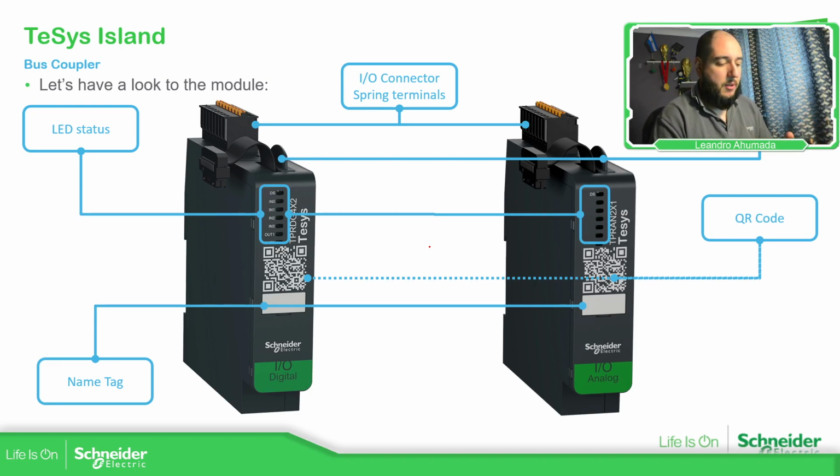Then we have in the back part the possibility to connect with the rail DIN. Over there, you have all the characteristics of the digital inputs and outputs. So, for example, for the analog inputs, you have voltage, current, you have, I just read it in front here, PT100, PT1000, thermocouples, and then for the outputs, voltage and current.